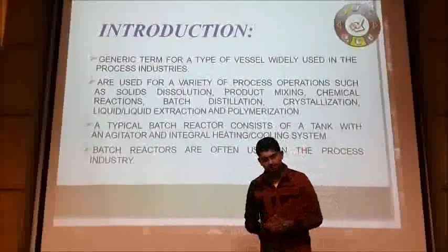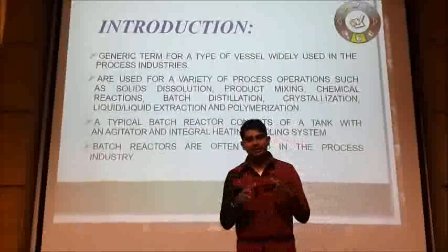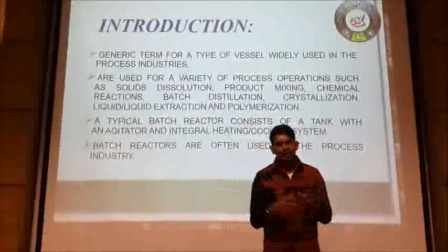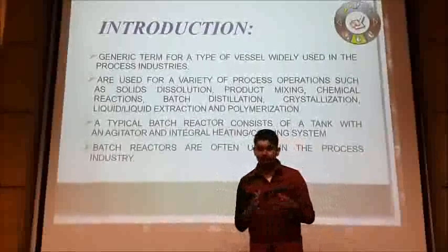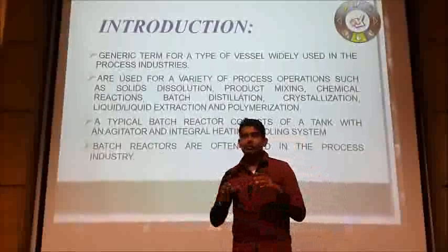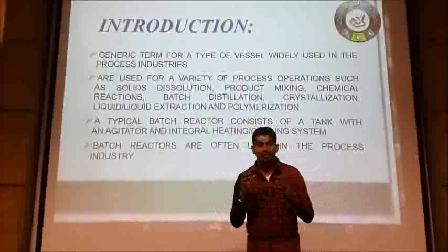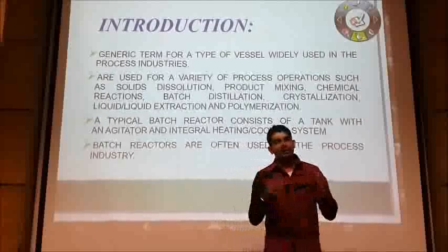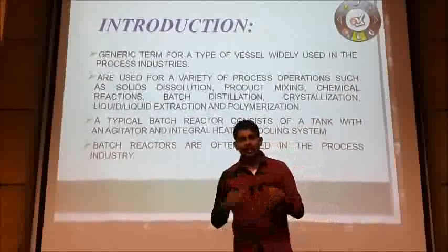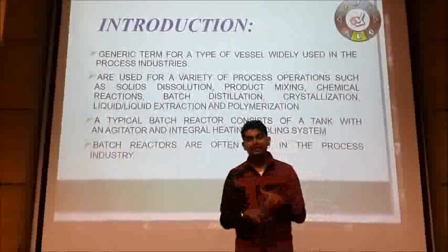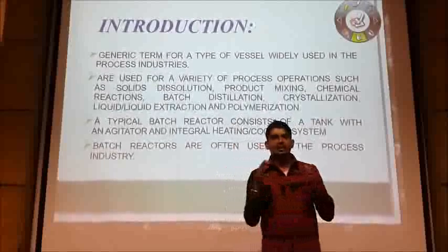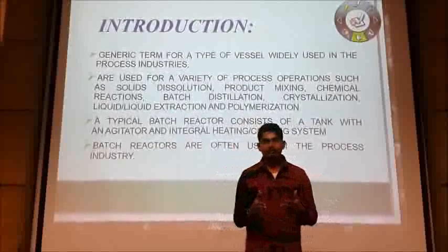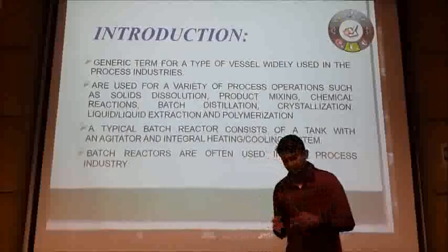So what is an agitator? An agitator is an impeller blade that is mounted on a shaft. A wide range of blades are used, and the blade covers about 2/3 of the diameter of the reactor. Where viscous products are handled, anchor-shaped impellers are used, which have a close clearance between the blade and the vessel walls.